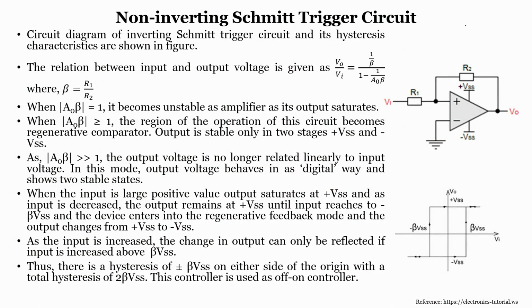As you can see here, the input voltage is applied to the non-inverting terminal. There is a regenerative feedback, positive feedback, and the hysteresis characteristics of this particular circuit is shown here.